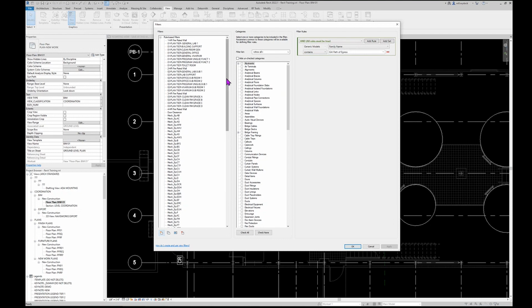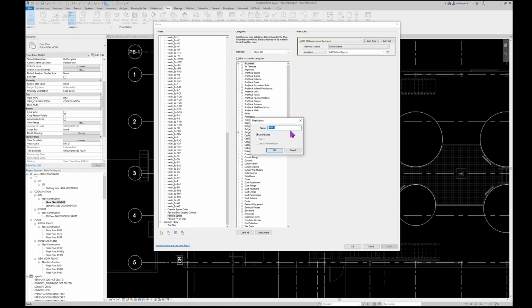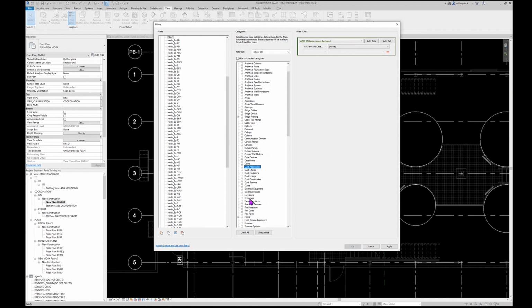When you create your new filter, the first thing you do is make your new one, and like I said, I'll explain the existing ones. I'll call this filter one for now. You always have to work from big to small. So big would be, what categories do I care about? In this case, maybe I only want to do stuff for ducts or pipes or something of that nature. I'll do pipes, that's what's on the screen. So I will click the pipes here.